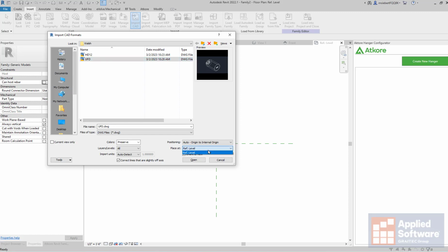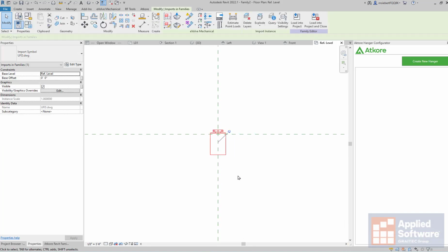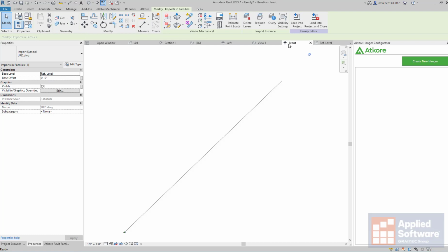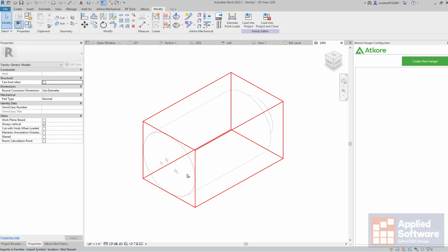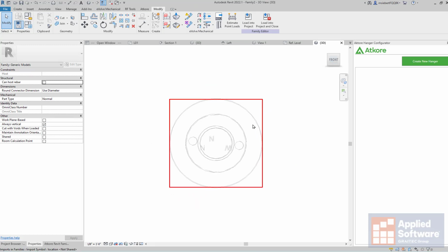Now you have a reference level, which is those reference planes you see on that X. So all it did was it just placed it right on that reference plane, so that way it's locked in at the insertion point. Now you can spin around this if you want to. You can try to find and put on a pipe connector so that way you can just connect up to this piece of equipment every single time.